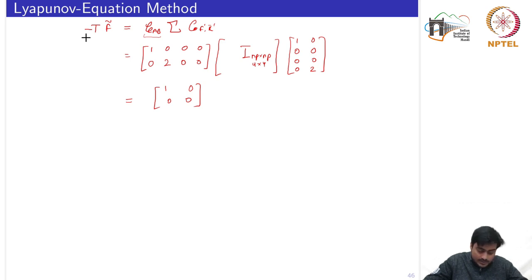So now the problem arises that either we keep iterating to find those K bar such that two conditions are satisfied: that the pair (F transpose, K bar transpose) is controllable and the matrix T is non-singular, or we should search for another design method by which we can compute the matrix K in one shot.